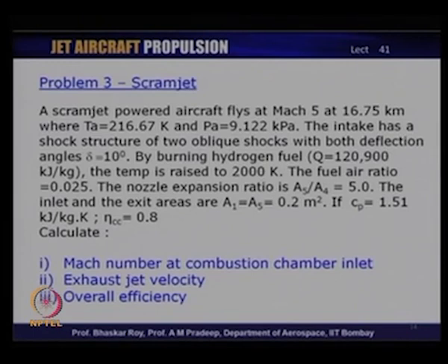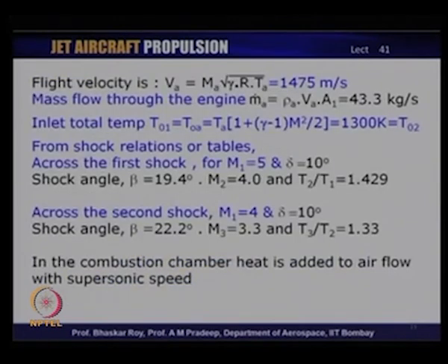What we will do is, we will find the exhaust velocity and then find the thrust and the SFC, and we will find the propulsive efficiency as we have done before for comparison of the various jet engines. The flight velocity for this particular craft can be now computed from the given Mach number, which is 5, and that comes out to be